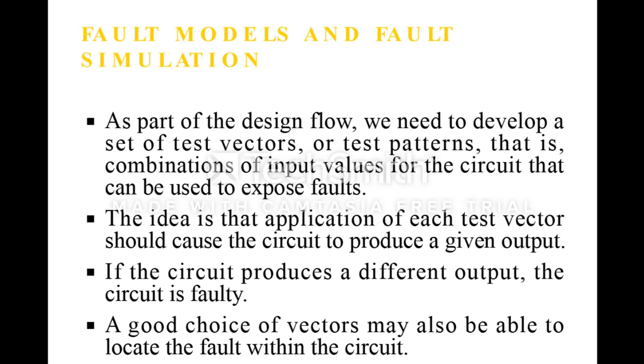Fault models and fault simulation. As a part of a design flow, we need to develop a set of test vectors or test patterns, that is, combinations of input values for the circuit that can be used to expose faults.